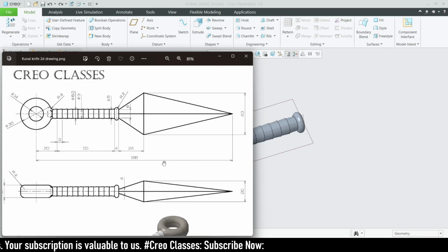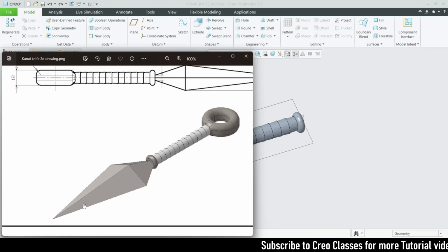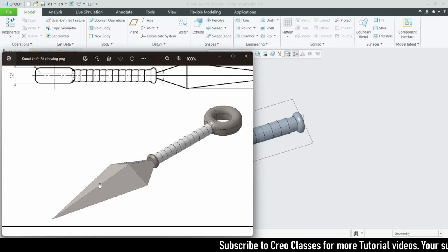So for this there are two ways. If you have a single sided extrude, if you have only this face extrude, you can directly extrude this as a rectangle and then create an extrude cut for this. But on this bottom face you can see that there is one more cut here, and this is kind of a sharp edge which has been created from a slanted rectangle.